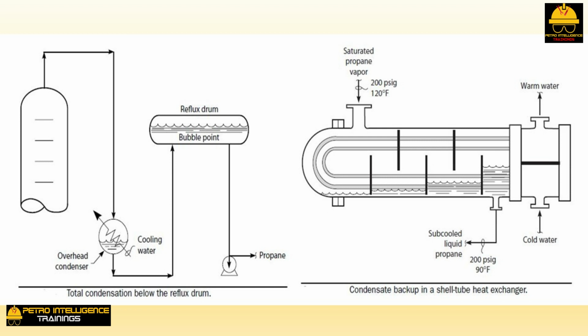The lower part of the shell will be cold. The transition point corresponds to the liquid level of condensate in the shell. The condensate level will always be higher toward the shell outlet nozzle. Again, this all applies only to condensers in total condensing service.